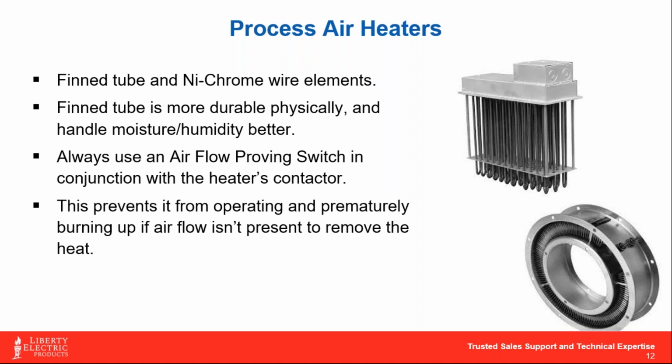The one thing I would definitely stress with air heaters as well is that you'll always want to put an air proving switch in line with your process. What an air proving switch does is look for positive air pressure, so that you couldn't have a situation where the heater is running and there is no air passing across the element, because that will burn it out. Just like we talked about with that cartridge heater, that buildup of heat has no place to go. So we either have to put it against a solid and transfer that heat, or we push air across it to cool the elements. So it's very important to use air proving switches.